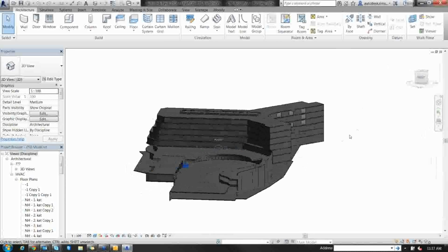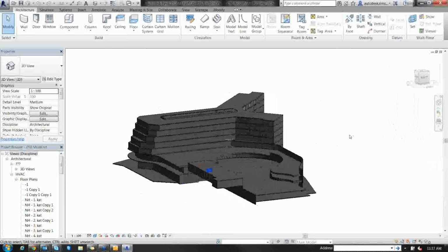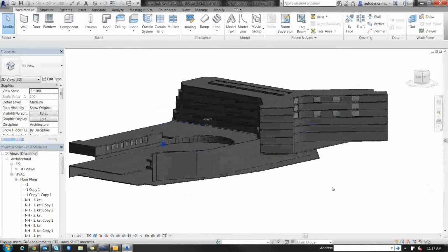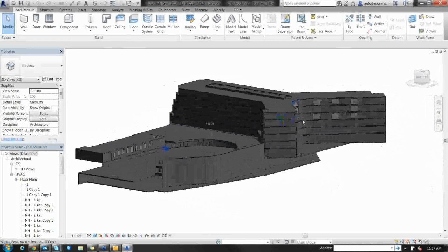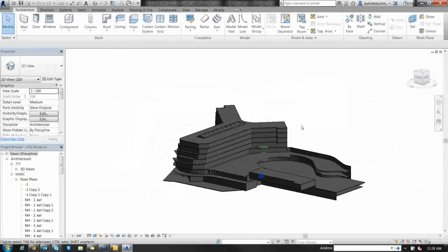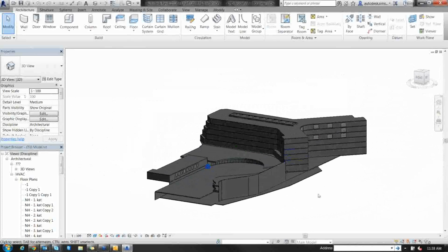All right, so this is actually a forum post, and it didn't come in initially as a problem in terms of geometry. And when you start looking at this model within Revit, for instance, obviously this is a very large building. It looks really clean, and nothing really jumped out at me. And they're actually having problems using the solar window approach. Once they turn on radiation, it's a little unstable.